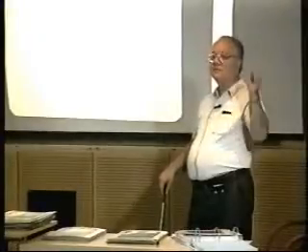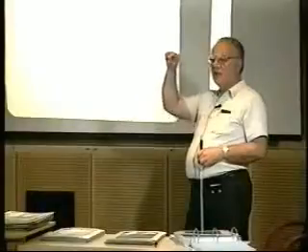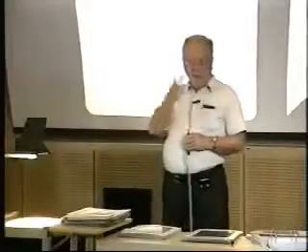And the reason it does is flow after flow. Okay? You have the transient, it's increasing sequence, so each of the transients of the previous flow adds another delta P onto each subsequent flow, so it pulls the points over to the left. We didn't have isochronal tests, so you couldn't get there from here. Okay? But the fact we matched all the superposition exactly, we would exactly reproduce the slope of the multipoint test, the flow after flow, when you plot it. I've got it here somewhere, but I didn't want to confuse the issue.